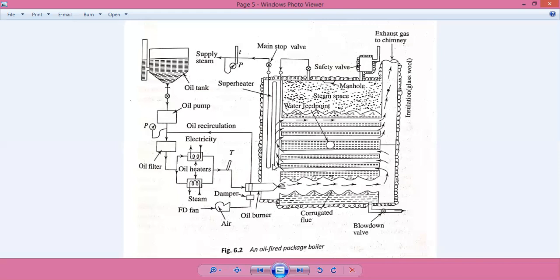Since the pressure in the furnace is almost atmospheric, caution is required to make the casing sealed against leakage. If the pressure inside the furnace is more or less equal to atmosphere, generally the leakage does not take place much. But if the pressure is higher, it produces more and more pressure over the walls. It should be properly sealed against any sort of leakage, because leakage of any steam and even flue gas causes a higher health hazard, as well as the total collapse of the plant itself. If you don't seal it properly, the hot gas will filter out, causing heavy energy losses and pollution to the atmosphere.